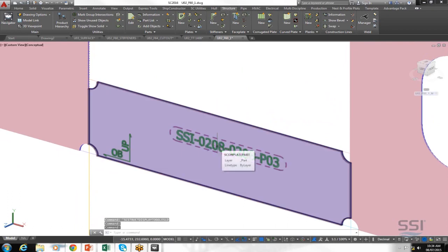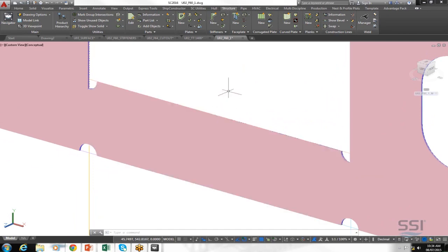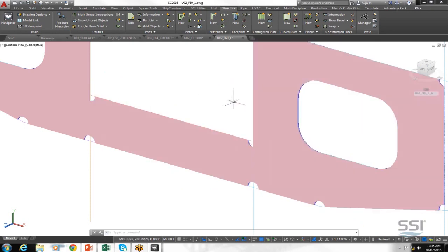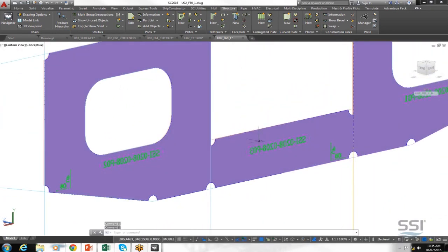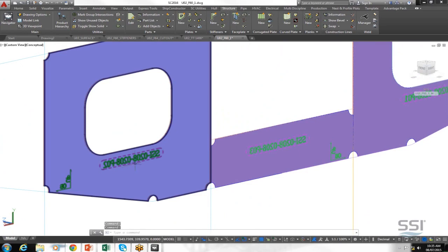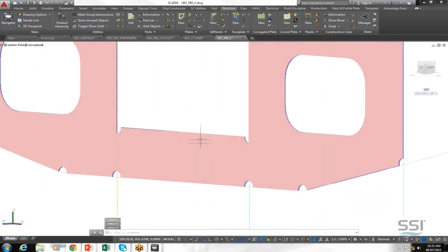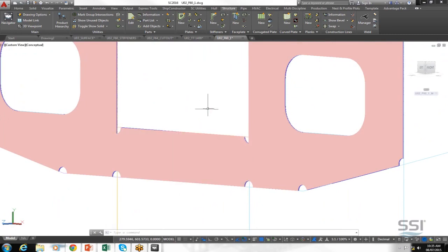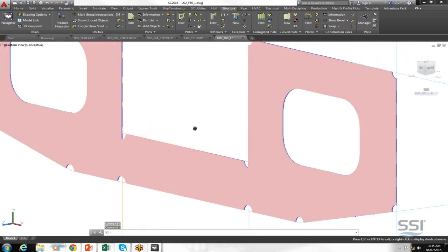I'm going to say you're seeing the piece mark, and I haven't explained this yet, as I hover over or select the part. What's happening is we're looking at it from the thickness throw direction. So we're looking at the plate, and we define the mark side as the forward side of the plate. If we rotate the image around, we can see the mark side is actually showing on the opposite side, but it's obscured when we're in the 3D view because we've got the solid showing in front of it. So now we have our panel,